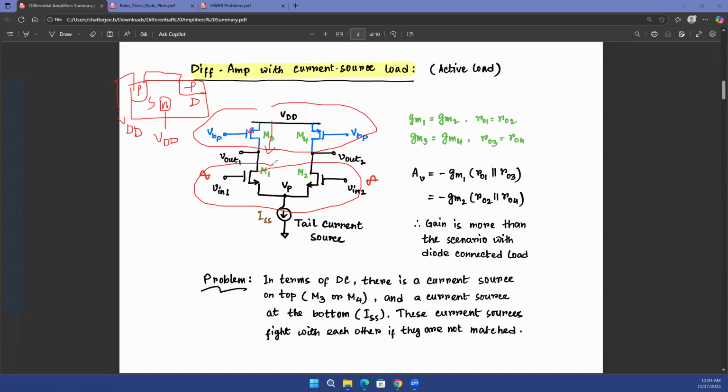Where would you connect the NMOS's body? You want to connect the source and the body together. But the source of one NMOS will be this midpoint, and the source of the other NMOS will be over here. Why would you connect the bodies of the two NMOSes? Those two are different points, right?